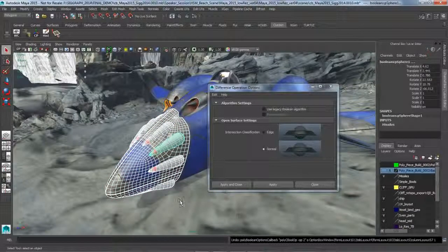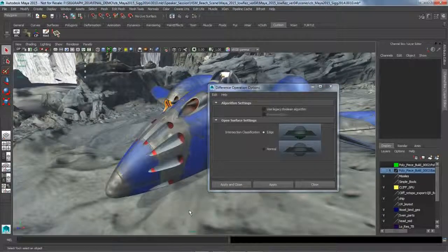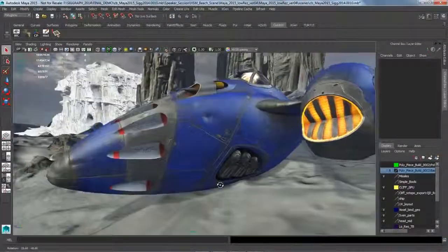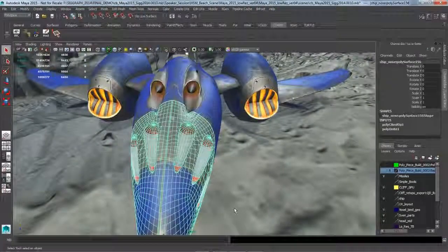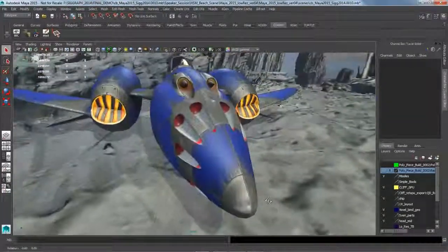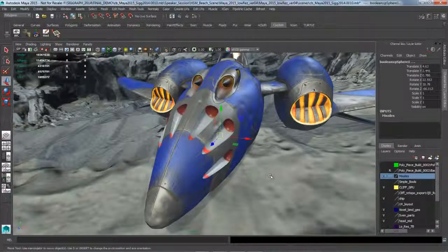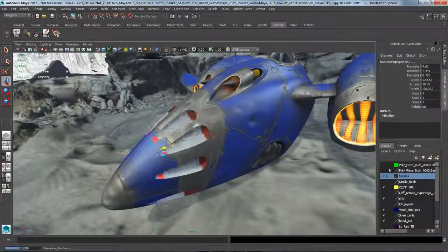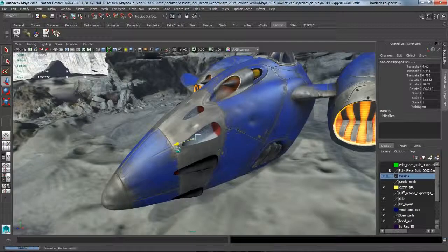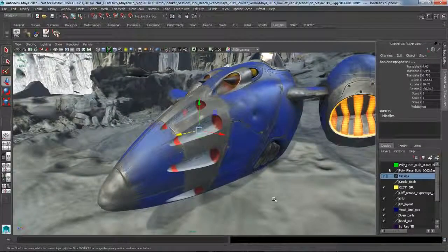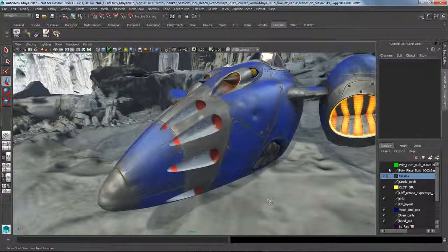But here's something interesting. Let's use the edge and let's use a Boolean of the geometry. Now, if I hit apply on that, you'll see that it's actually effectively transferred or brought that texture over from that object into this object. So I now have that missile texture transformed in there. Now, if I grab all those missiles again, this is where I could start to begin to change, transform, scale, rotate, whatever it may be. I just wanted to show that this is a different way you can work with Booleans. You can get that trim effect, but you can also transfer textures effectively over as well.